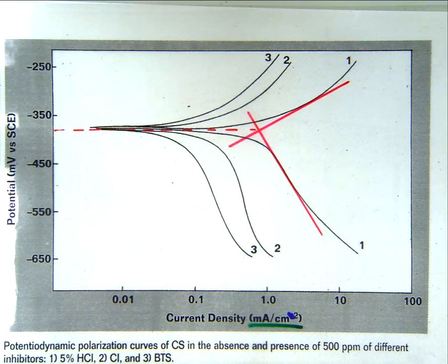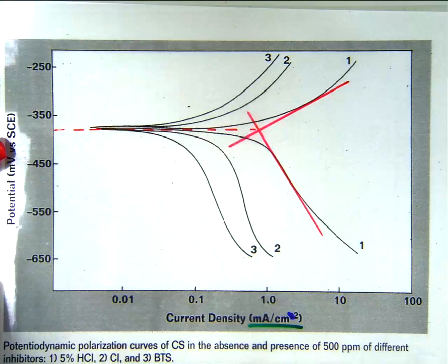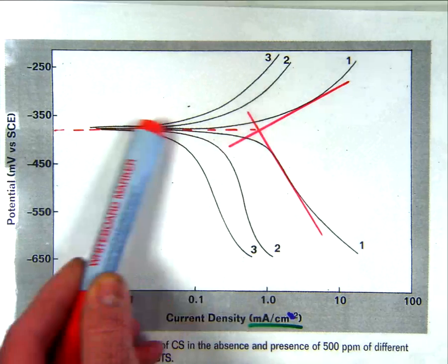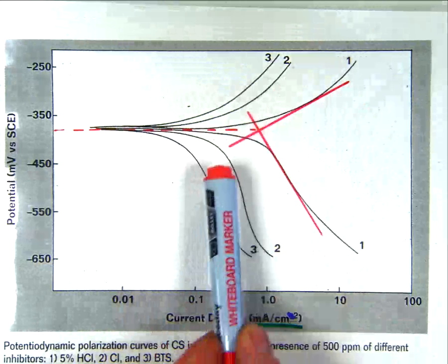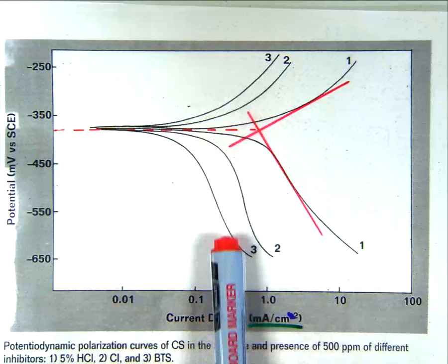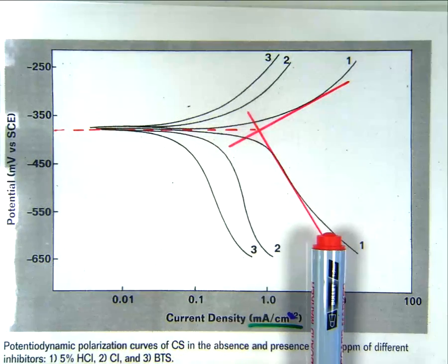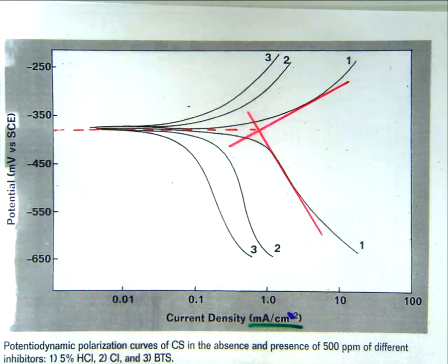The third plot is for what was brand new then, a new corrosion inhibitor, which is a benzaldehyde thiocarbazone, which I'm sure you didn't really want to know, but I like to keep trying that as a tongue twister. What the graphs are illustrating is that the new inhibitor actually gives you even lower current densities than the old inhibitor.